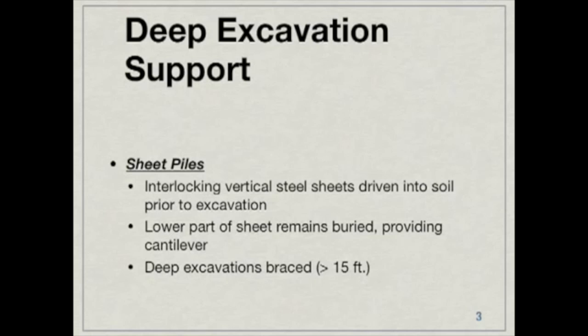In the previous presentation, we discussed self-supporting sloped excavations. These excavations are fine if you're not restricted. However, in restricted areas, in other words, an area where buildings are adjoining to where you're trying to do your excavation, you're going to need some type of support.